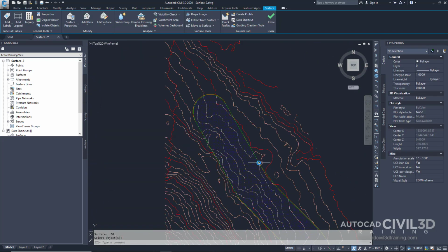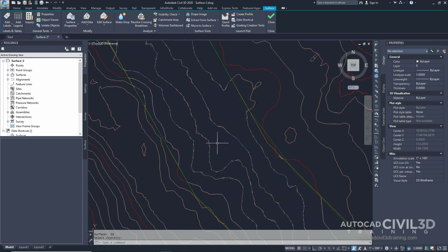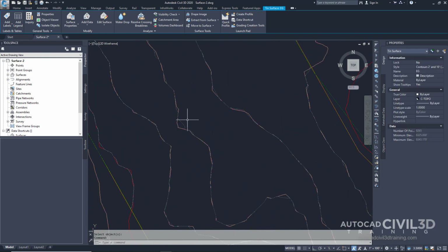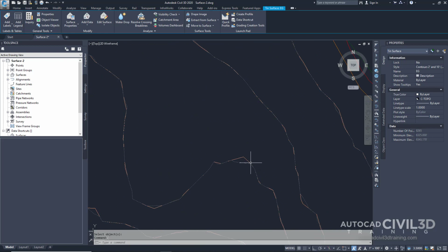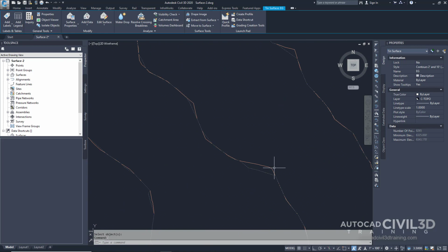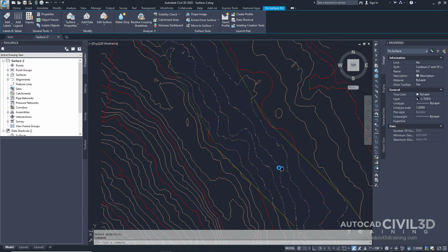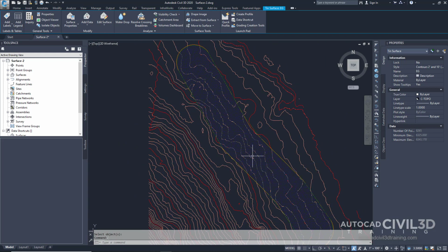Now currently, the amount of points in this area, which you can faintly see in blue, is not as dense as it was before. Now the new gray surface contours that we have right here match our original polylines fairly close to what we originally had. You can see the little deviations that we have right here. Now the Simplify Surface command can reduce the amount of data that the surface uses without sacrificing much of the surface accuracy.